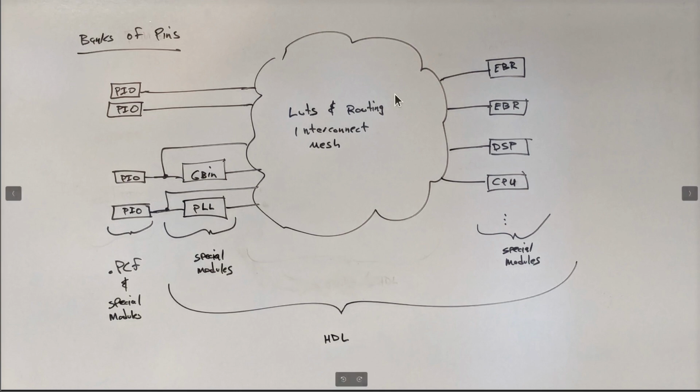They just have a different quantity of them. So your Verilog will be very, very portable. PLLs, G-bins, and block RAMs, stuff like that, and even DSPs and CPUs would be, if the chip had them on it, and if they were from the same vendor and the same chip family, they would have very similar, if not identical, modules. These IP blocks, as they're often called, would be the same. But you change the package.